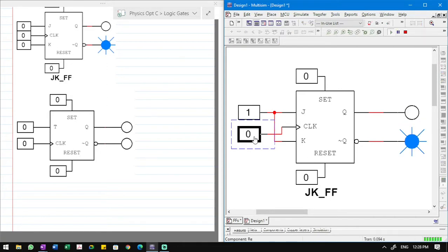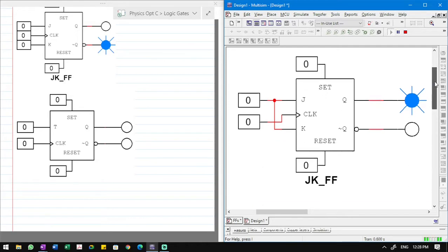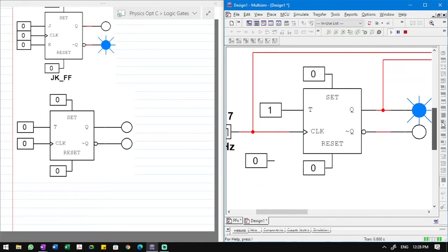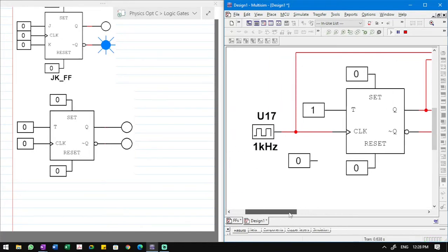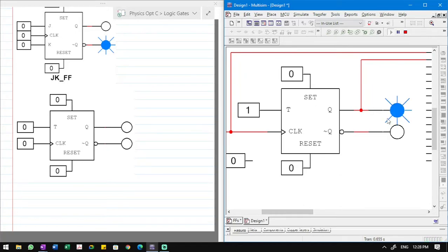Right, so the clock is controlling it once J and K are on. J and K are now controlled by one input, right? Once J and K are off, the clock actually loses control. Now, this connection of the JK flip-flop, where J and K are tied together, is another, very specific operation of the JK flip-flop known as the toggle flip-flop, or the T flip-flop. Now there are not really race conditions here.